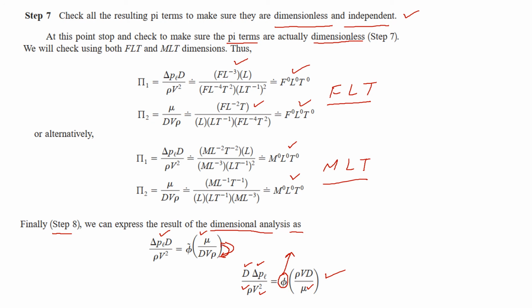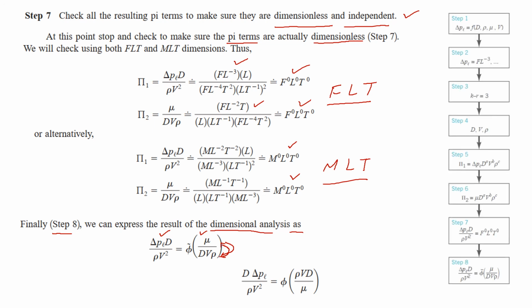Then we will fix this value of the constant, and then we will use this equation to see the combined effect of diameter, density, viscosity, and velocity on the pressure drop per unit length. And this will make our experimental analysis much easier, because as we initially mentioned, from 10,000 experiments we are reduced to quite a few experiments. So this is how we have done our dimensional analysis.